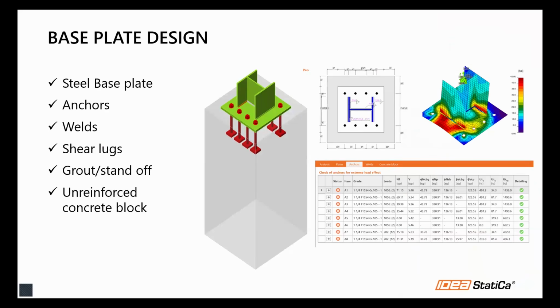Currently, and what we've had in the past with our Connection application, is you're able to design the steel base plate, the anchors, welds, shear lugs, including a grout bed, standoff distance, and then the unreinforced concrete block. So if we look at some examples of this,